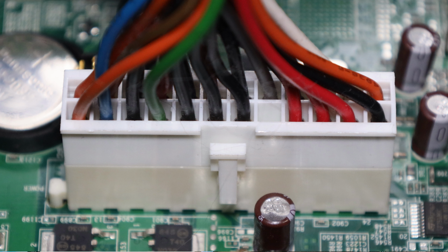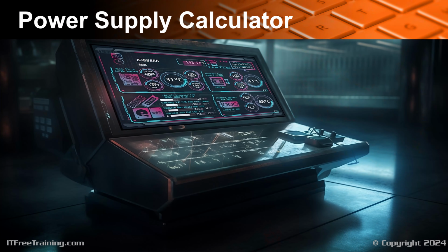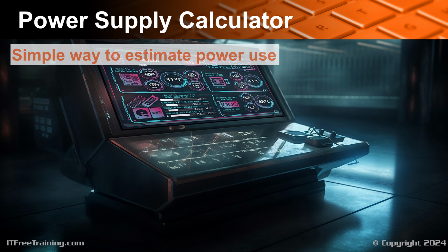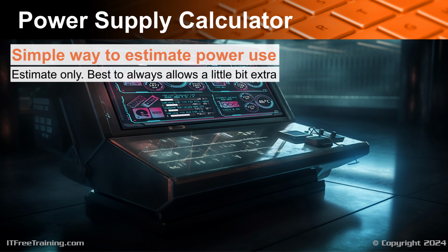We've had a good look at power supplies. Now let's have a look at how to work out how much power you'll need. You can do the calculations manually, but there are a lot of power supply calculators available nowadays. These calculators make it simple to estimate how many watts your power supply may need. It's an estimate, so better to allow a little bit extra.